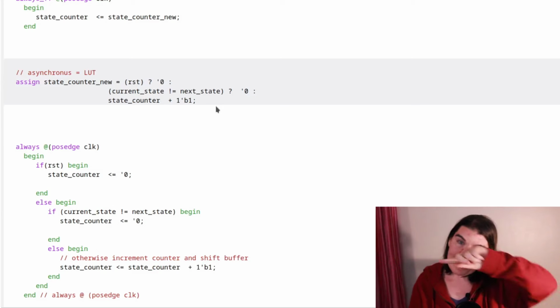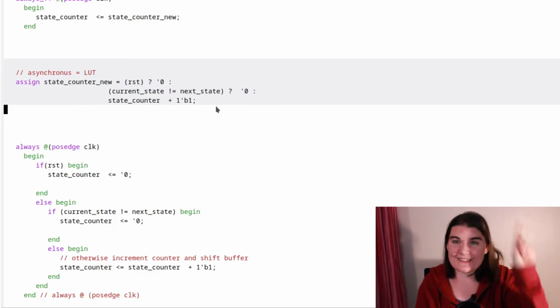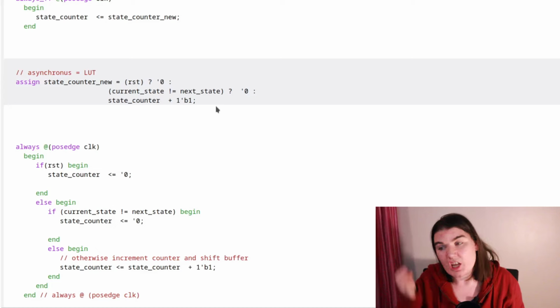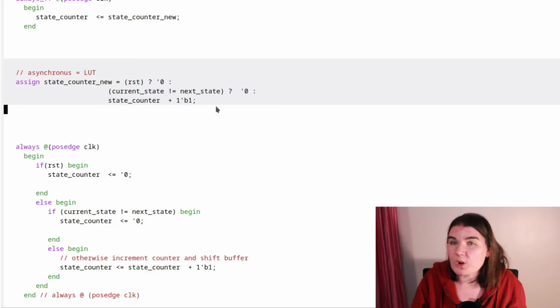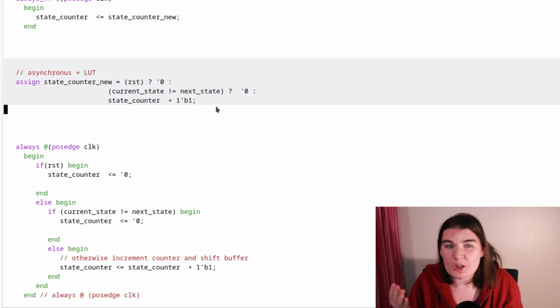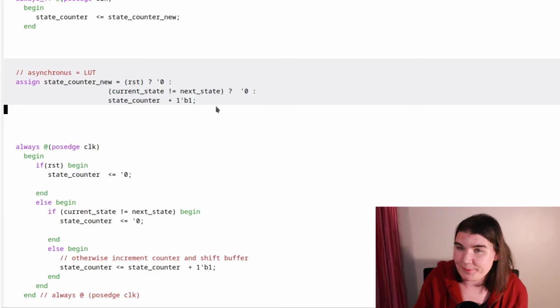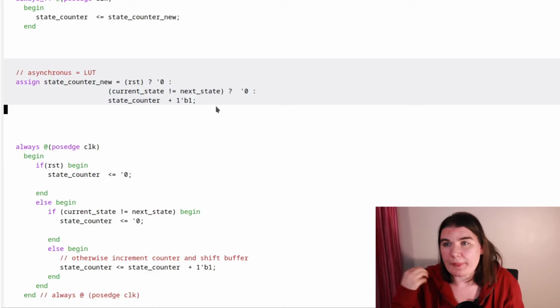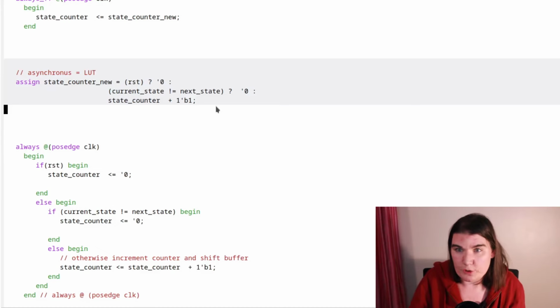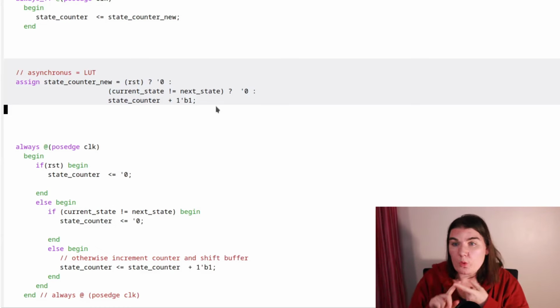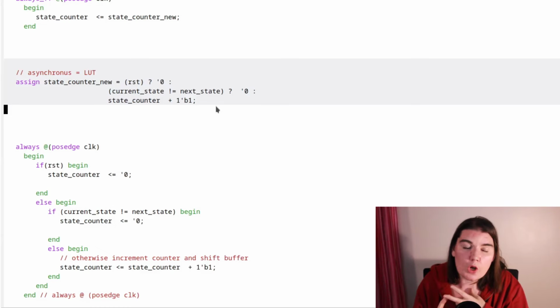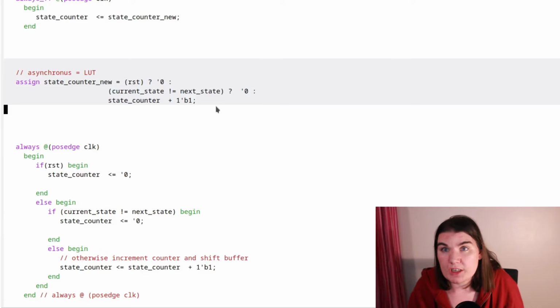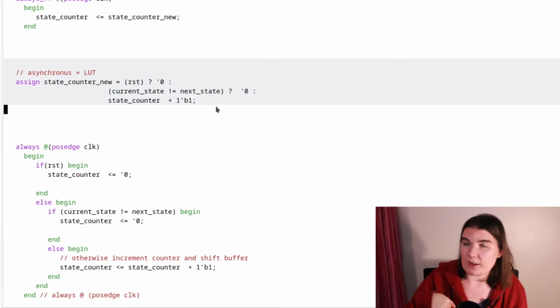Synchronous logic can loop back on itself because the register will be inside the loopback path. Asynchronous logic shouldn't be looped back on itself because then the static timing analysis tool is not going to be able to know how long the signals are. The tool is going to put a hacky memory element inside the loopback path, and that hacky memory element is called an inferred latch, which means that all of your default cases and all of your cases for the behavior of a signal need to be covered in asynchronous logic in order to avoid looping a signal back on itself.